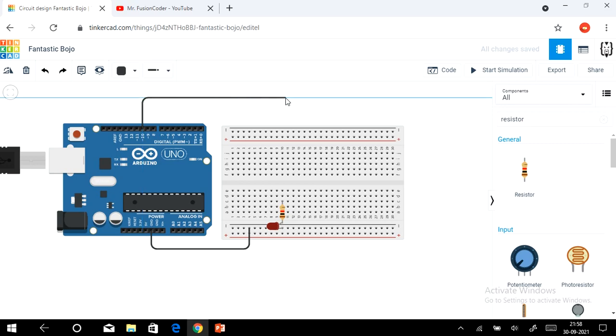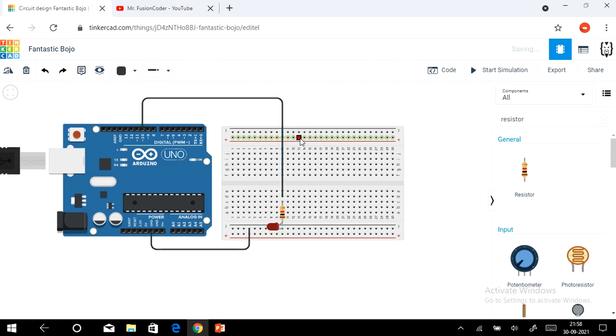You can make it organized like this. It looks good. Okay, and leave the space. Don't always connect it completely with the resistor. Leave a gap and then connect it over here. I hope you understood what I said. They should not touch each other. They should be on separate dots, because after all the whole lane is connected, right? So that is the same meaning of connecting together.